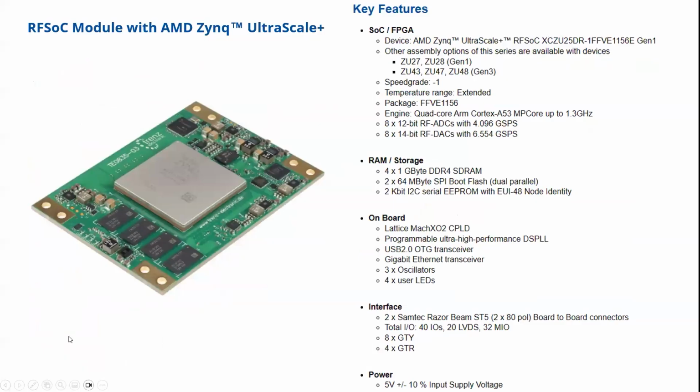Applications of this system on a module might be when you're looking for drones, and you need to be looking at the RF frequency that they might be using to communicate. Or if you're in a certain environment where you're trying to say, well, there shouldn't be any cell phone communication in this environment, you can use the RF sampling to look at those frequency domains and figure out what's going on. Or if you have a noisy system and you're trying to do some debugging, maybe you need to be looking at the RF frequencies that your system is emitting that didn't pass your environmental qualifications.